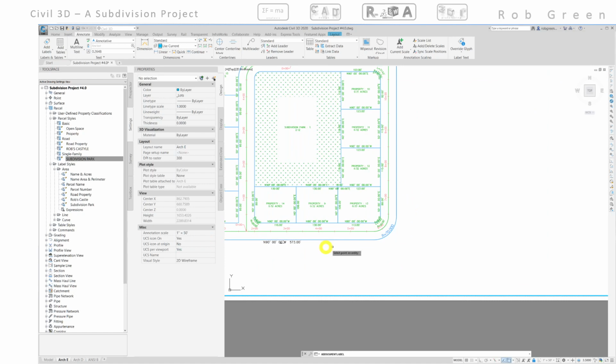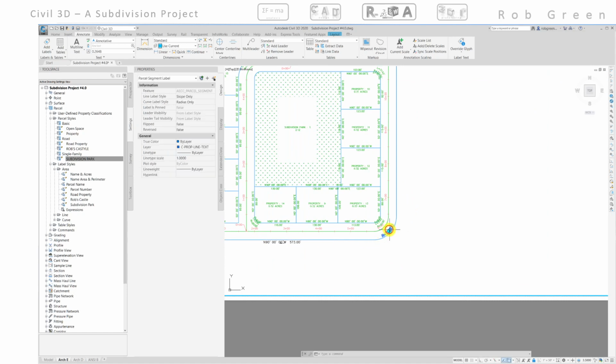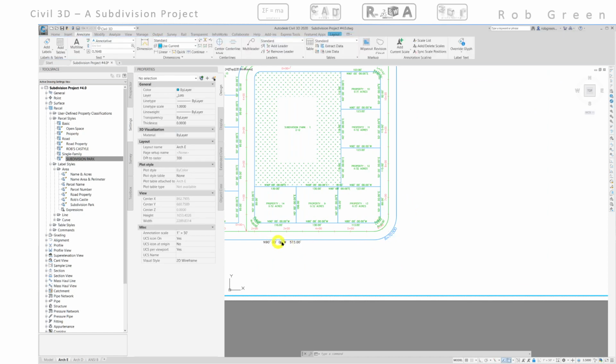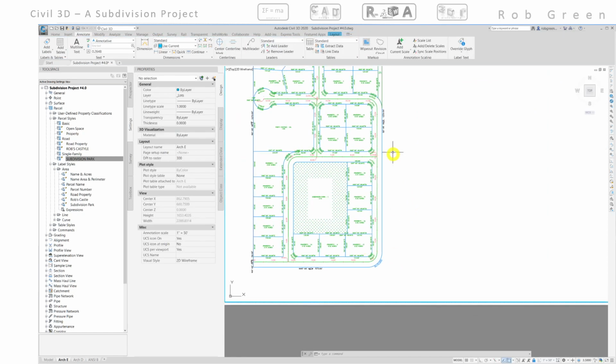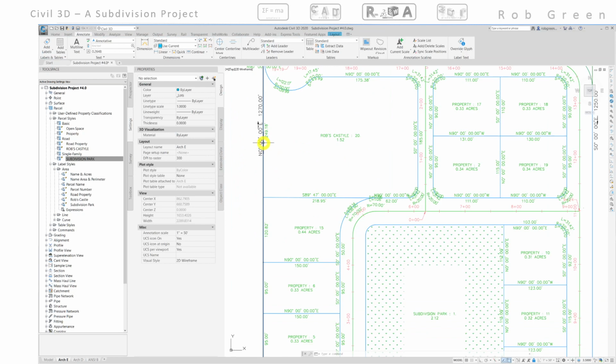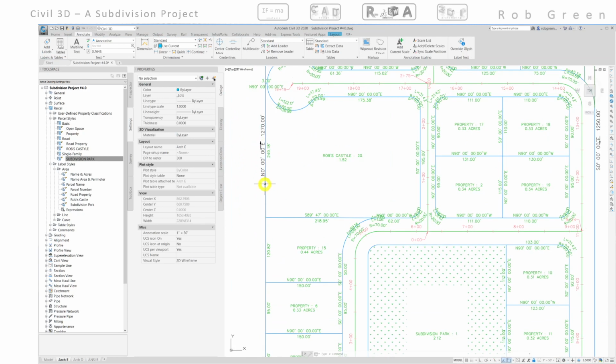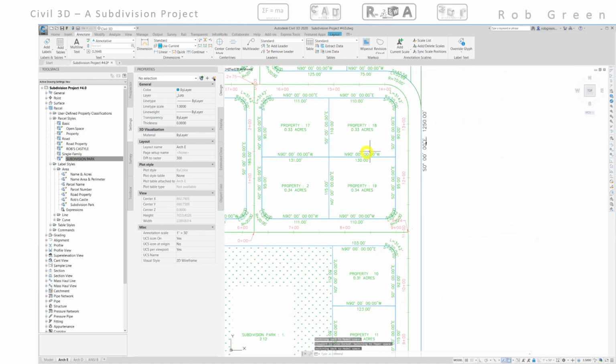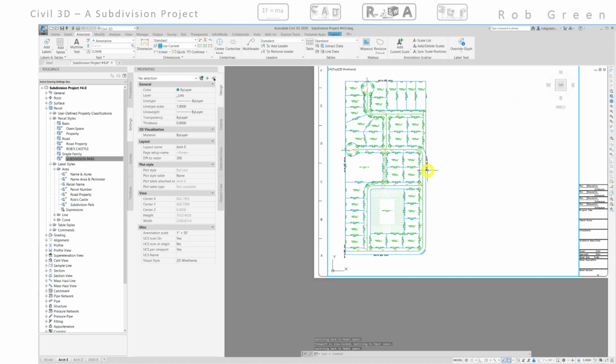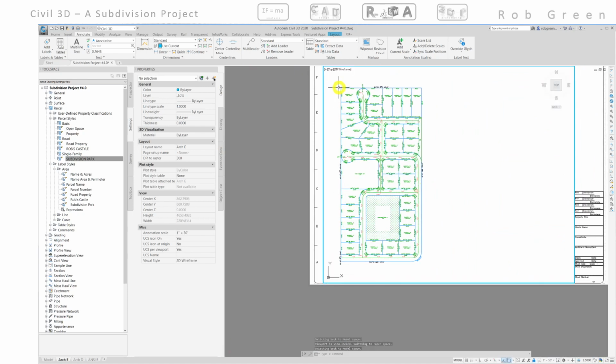So I don't like where it's at, so I'm going to select that thing and flip it. Now it's on the outside, indicating, right, these outside dimensions are what go all the way around. So what I want to highlight is, notice there's an arrow here. North is my prime axis and east is my offset. Notice over here the arrow is going the other way and south is my prime axis. So as I pick the direction of point 1 and point 2, it defines what my prime radius is.